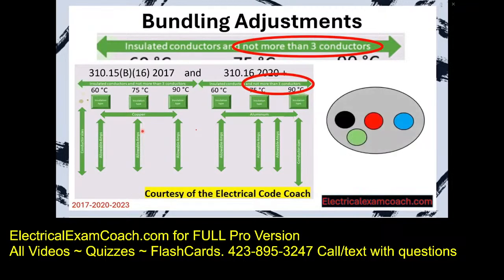Let's imagine that we have a piece of conduit here and we pulled in a black, red, blue, and an equipment grounding conductor. What this table is saying is that those ampacity values listed down below in this table are true as long as you have not more than 3 current carrying conductors in a cable, pipe, or raceway. If you do have more than that, then we have to do what's called a bundling adjustment.